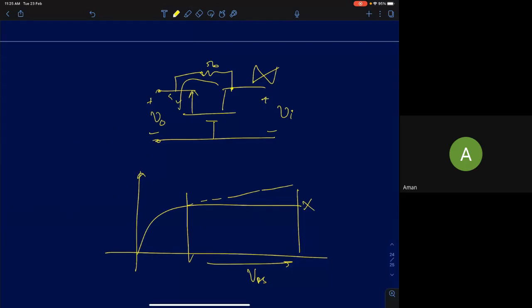One of you is asking what happens if VD is less than VS. First thing, in an amplifier, we will never let this condition happen, because we have configured an amplifier to extract a gain out of it. The moment VD becomes equal to VS, the current through the MOSFET will start going to zero. Yes, its drain and source terminals will get interchanged, but we will never let this happen, because we have clearly ensured that the output voltage is fixed. You will be connecting a load resistance to that, and you will expect to deliver power to the load resistance. So you don't want drain and source terminals to change suddenly with input signals.